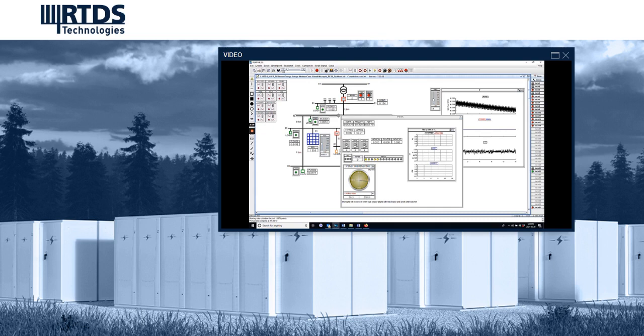To make the voltage of the microgrid be within the criteria of the synchronization voltage of the grid, switch capacitor banks are enabled to bring the angle difference to a set criteria. Then once the microgrid phasor aligns with the grid phasor, the microgrid will be reconnected back to the grid. So now we can see that the microgrid has synchronized with the grid and it's back to grid connected mode.